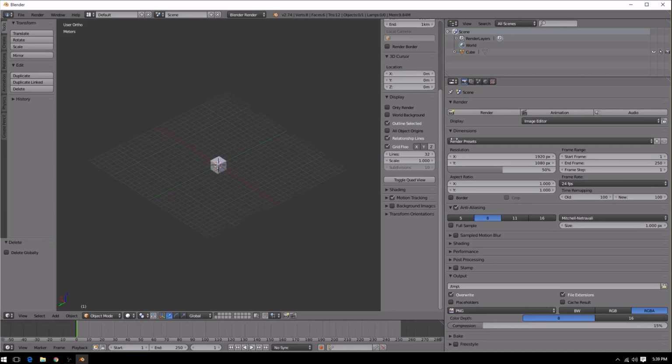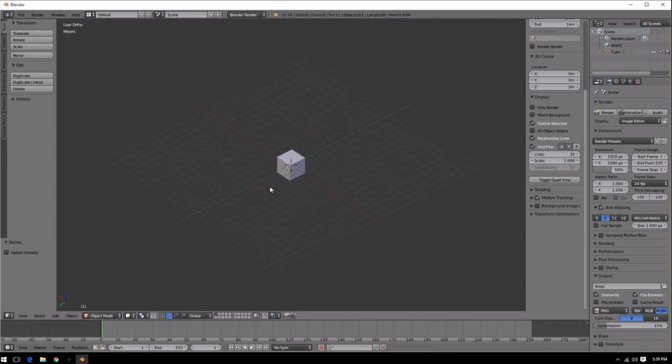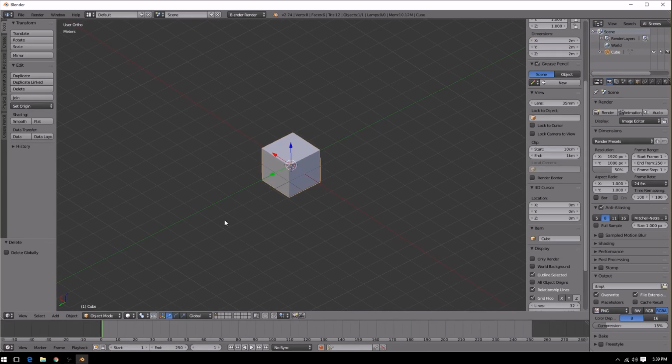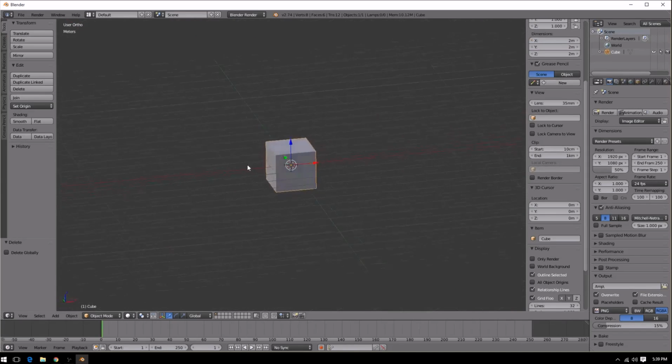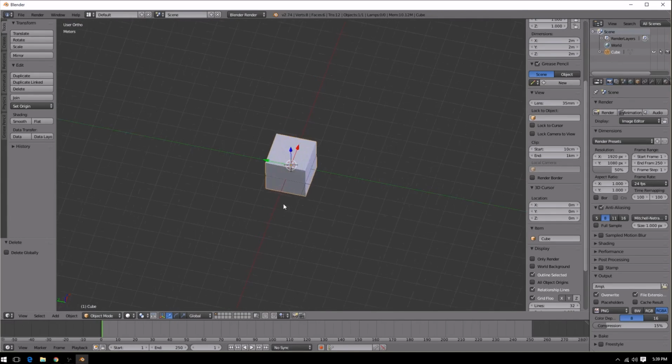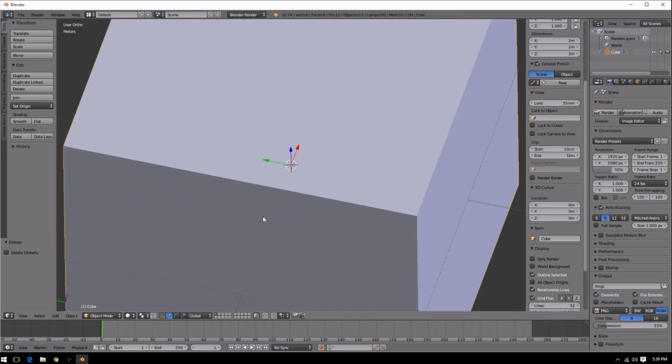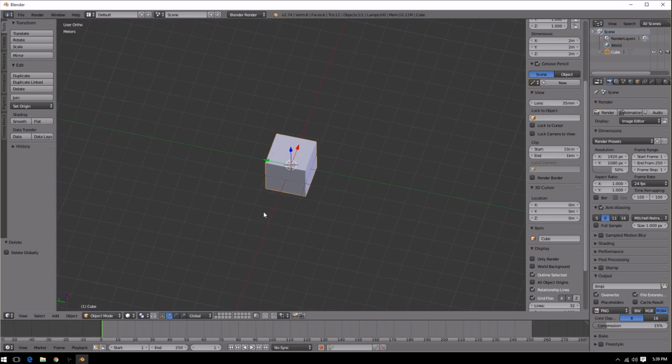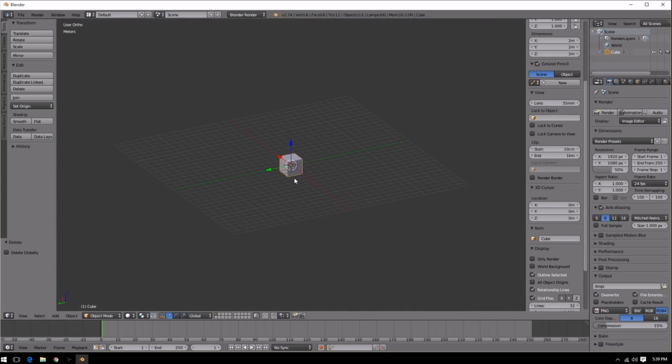If you wanted to scale this cube to begin modeling and to start getting this thing kind of building size, right now the default cube always sets up at 2 meters by 2 meters. So we're basically a very tiny little item right now. If we loaded this into the game, we would have maybe a very tiny small little object. You'd have to zoom in big time to see. So right now what we'd like to do is scale this default cube so we can start working with it as a building.